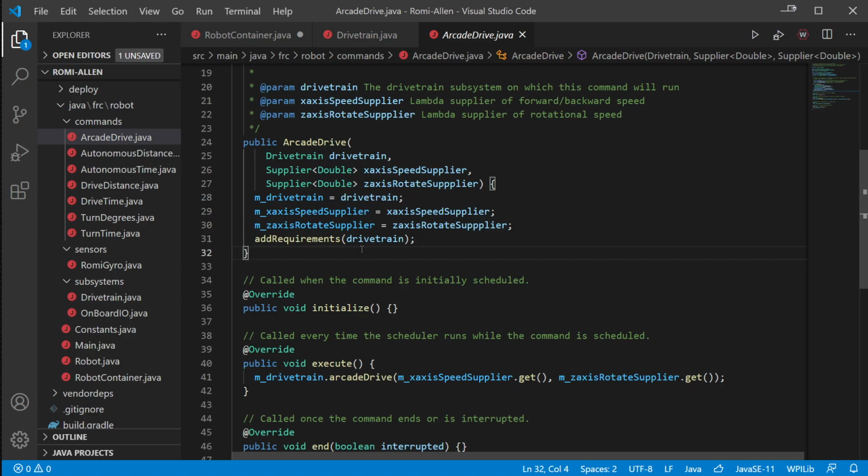The motors get unhappy. You have things like twitching back and forth. That is one of the errors that you will see sometimes, especially if you have really twitchy motors, where it looks like it's telling it to both go forward and stop at the same time. It's possible you have two commands trying to drive that same motor at the same time.